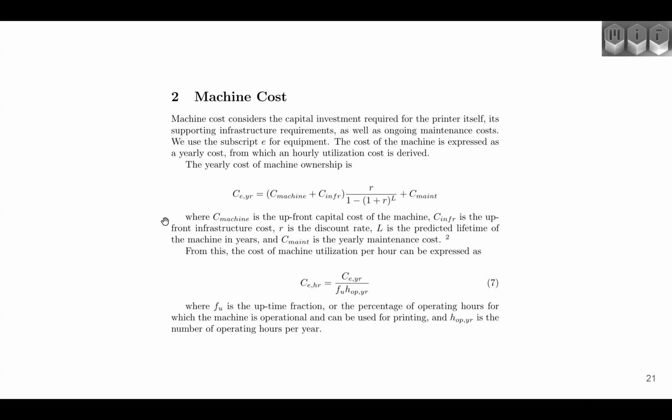And then, of course, in order to get our hourly cost, I don't just take the $10,000. So go over the previous example: $70K machine cost, 7-year depreciation schedule, straight line. It's not like, oh, my machine costs $10,000, then I divide 10,000 by all the hours in a year. I have to divide that by the number of working hours. That's going to be a function of my shift schedule. That'll also be a function of your assumptions on uptime, downtime, planned maintenance, those sorts of things. When I mentioned previously that we're going to treat things as non-dedicated equipment, hopefully now that starts to make a little more sense what I mean.